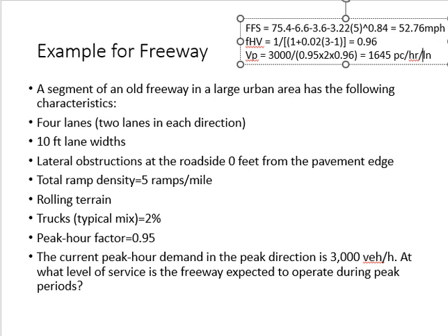Now we are trying to find out level of service. For level of service, I must know density. Density is flow rate upon speed. Do I have flow rate? We just found it, right? VP is the flow rate. Do I have speed?